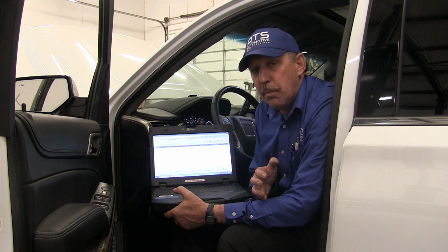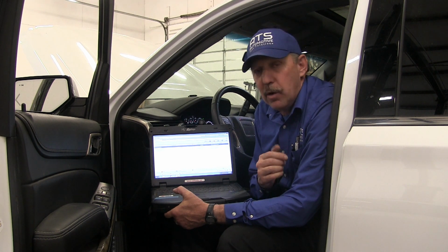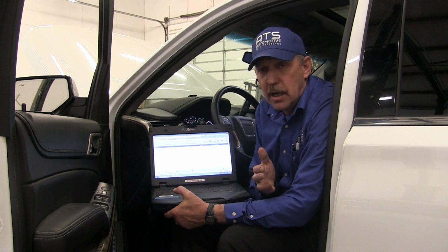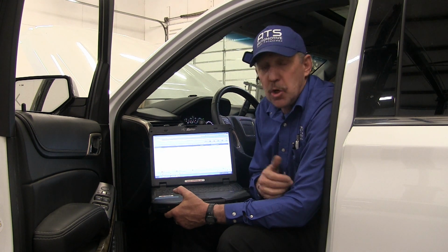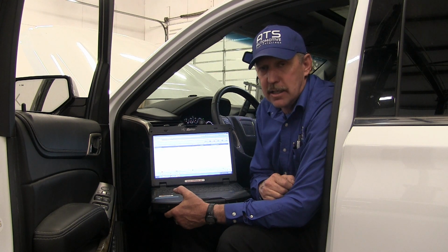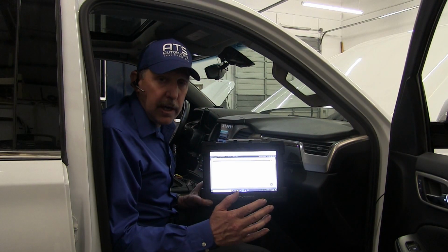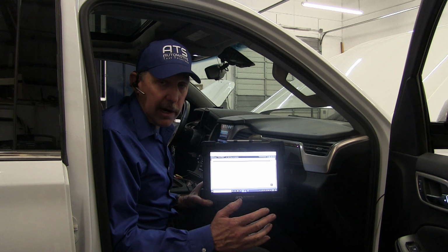What we need to do now is I want to get a wiring schematic out, and I want to get a scope, and I want to get up on the camera, and we want to make sure that our bus lines are okay. This should be CAN bus, it's high speed, so let's go ahead and take a look at what we have connected to this camera. Okay, so now what we need to do is get a wiring diagram.